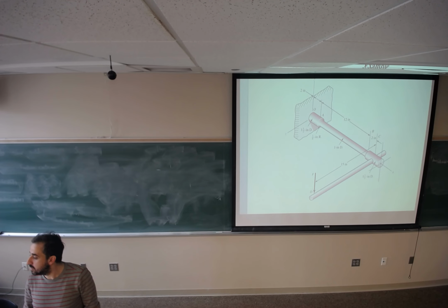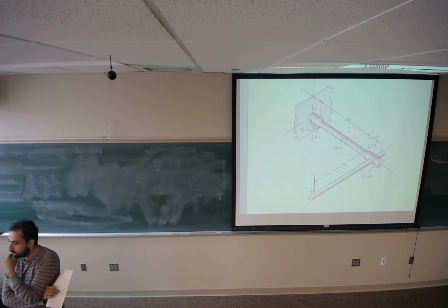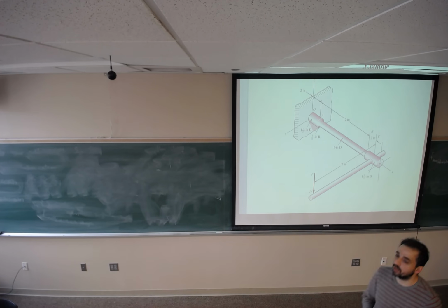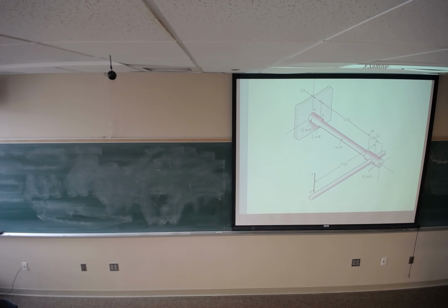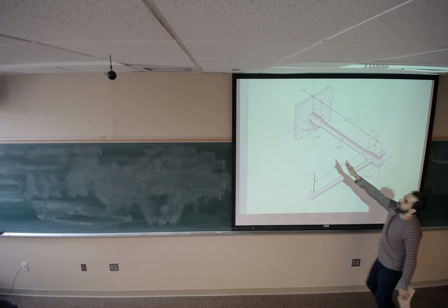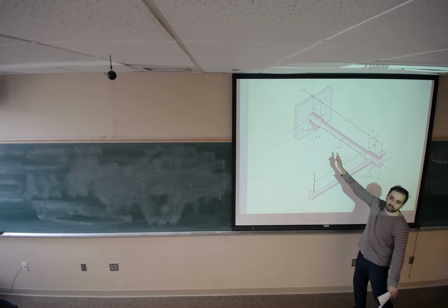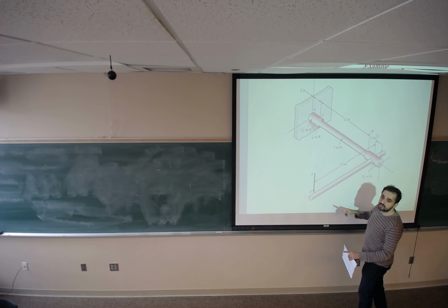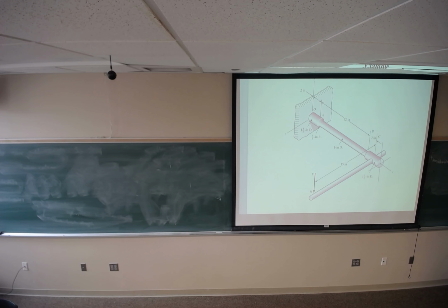Why is that? You're having pretty much all the forces going through that point, and it's necking down to a thinner diameter. Okay. Point A definitely is going to be one of our candidates because it's going to have the smaller diameter. We should check that. But also point O should be checked because it's going to get more moment and torque, because of this force. Also point O? Point O, okay. Sorry, you said point A again. Point O and point A would be our candidates.